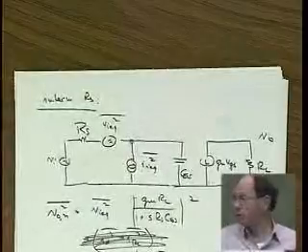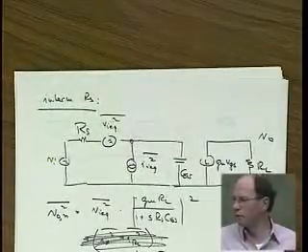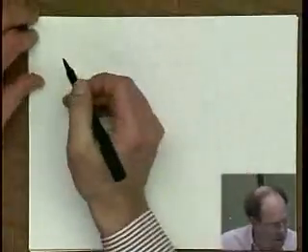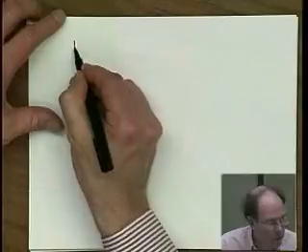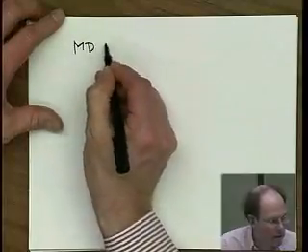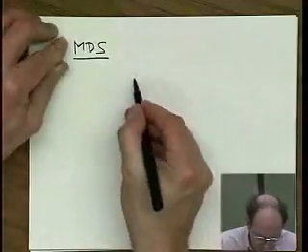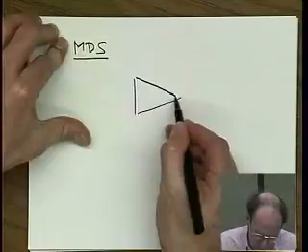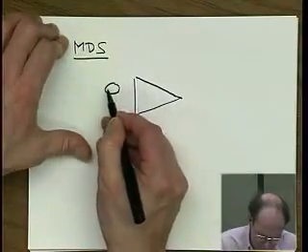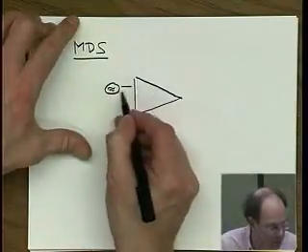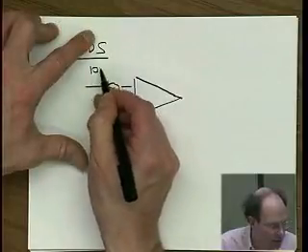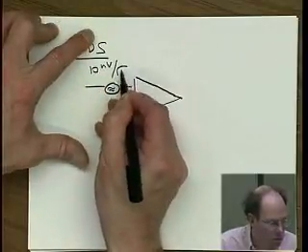But if you're the manufacturer of an op-amp or so, then you don't have that opportunity. Sometimes they specify the correlation factors and so on, and then other ways to take care of them. Okay, so very closely related to input referred noise is the so-called MDS, minimal detectable signal. Suppose that you have an operational amplifier that was spec'd in the data sheet as having an input referred noise voltage of 10 nanovolts per root hertz, for example, right?